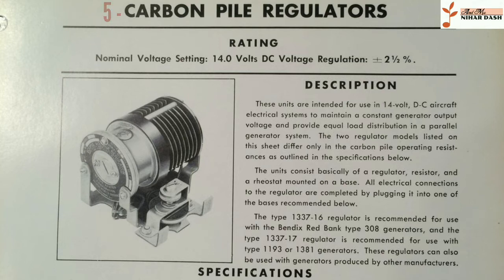A carbon pile resistor can also be used as a speed control for small motors and household appliances, sewing machines, handheld mixers, with ratings up to a few hundred watts. A carbon pile resistor can be incorporated in automatic voltage regulators for generators, where the carbon pile controls the field current to maintain relatively constant voltage. The principle is also applied in the carbon microphone.